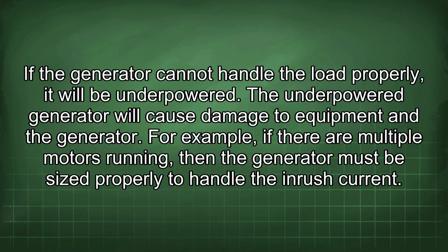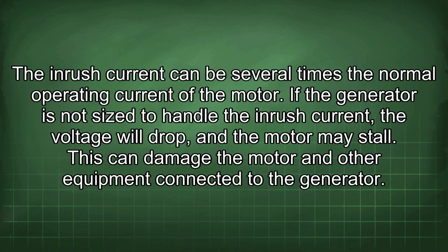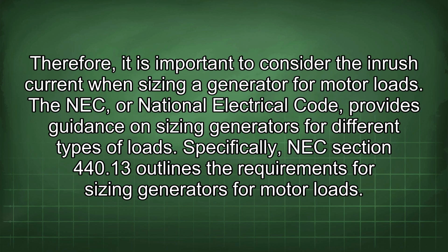For example, if there are multiple motors running, then the generator must be sized properly to handle the inrush current. The inrush current can be several times the normal operating current of the motor. If the generator is not sized to handle the inrush current, the voltage will drop and the motor may stall. This can damage the motor and other equipment connected to the generator. Therefore, it is important to consider the inrush current when sizing a generator for motor loads.